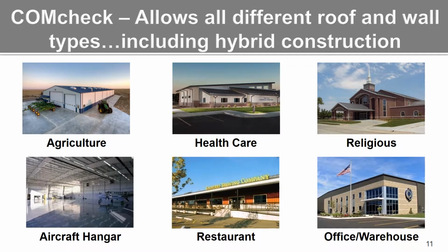The software allows you to break apart various portions of the building, and if you use ASHRAE 90.1, you may not be required to increase the levels of insulation for the semi-heated space areas. We reviewed all that in parts 1 through 3 on the space conditioning types and how to navigate energy codes.